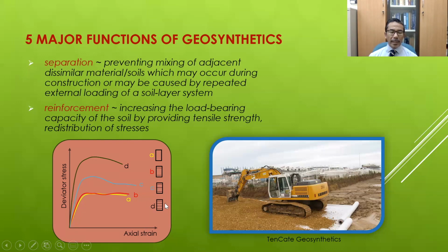For sample D, we can see that as the stress is increased, the axial strain also increases, until a certain point, beyond which the strain will continue to increase without any increase in stress. If we compare the curve produced from sample D and the curve produced from sample C, sample D produces a higher strength.